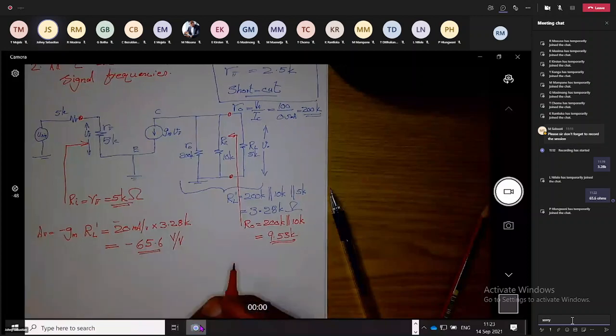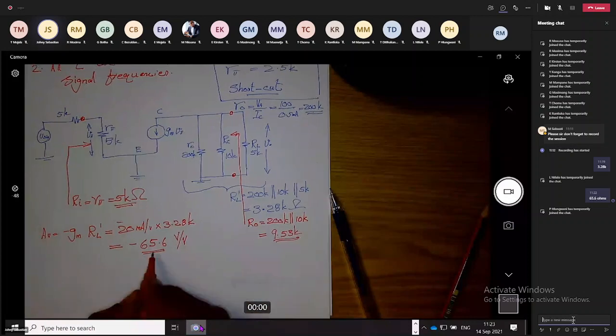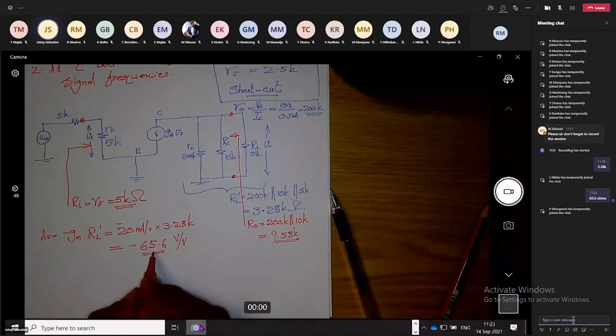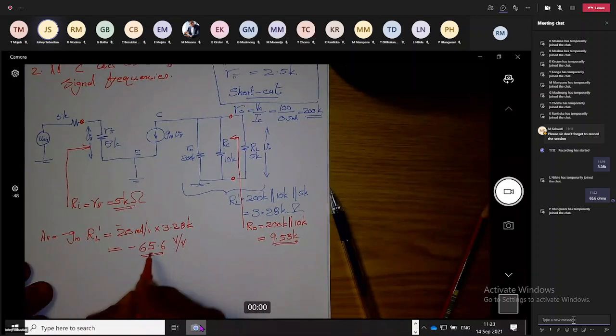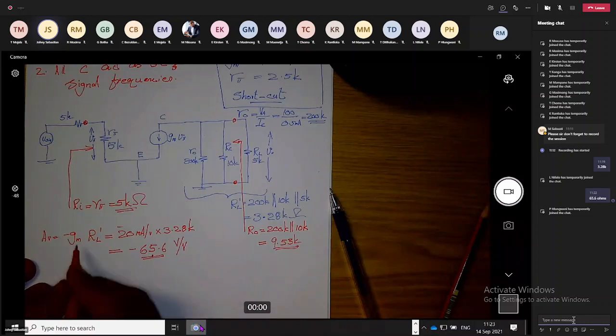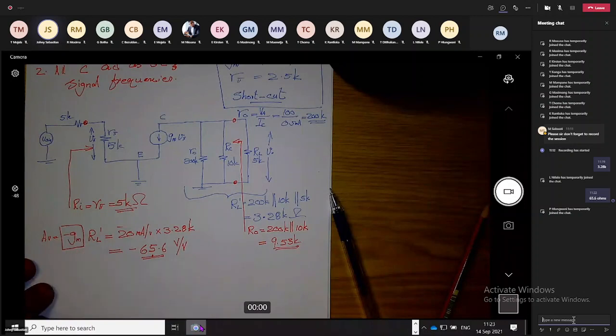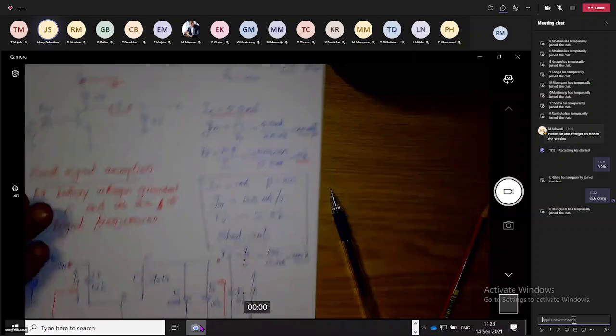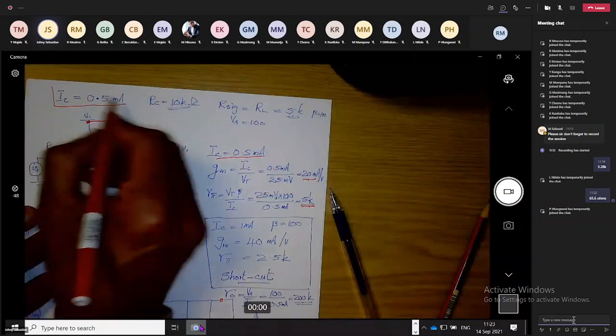So for this problem, voltage gain actually reduced. We had voltage gain 97.56 yesterday for the first part of the problem. Oh, sorry, 4.17. Why did the voltage gain reduce? This is the reason. GM became half. Why did GM become half? Because IC reduced into half